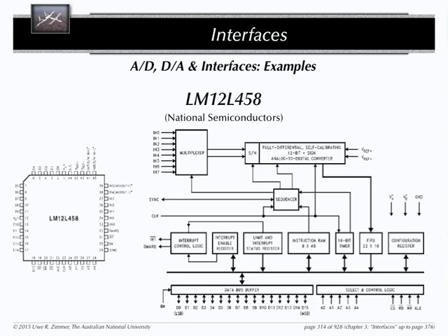The lineup down here is basically what you will expect to see in these 32 words when you look at it from the CPU side. Some of these words will be a configuration register. Some will be an instruction RAM. So 8 memory cells in sequence which give you this information you want to program this thing with.